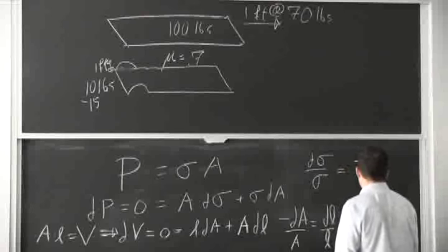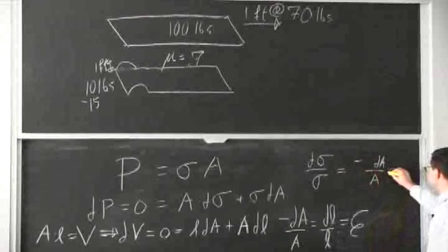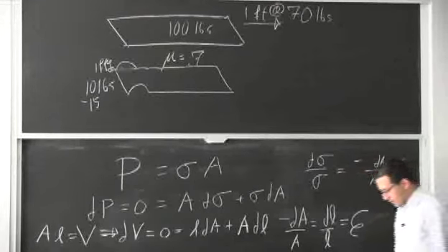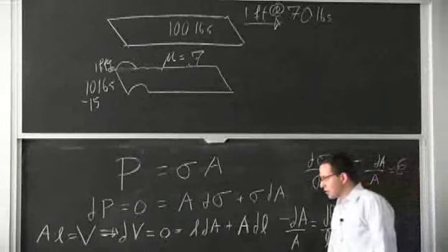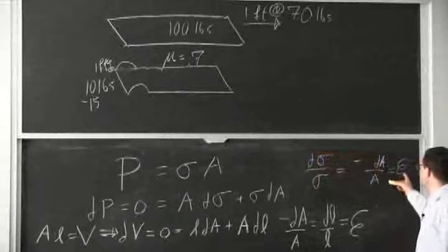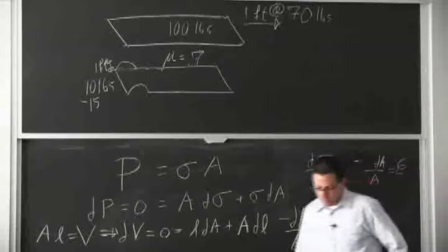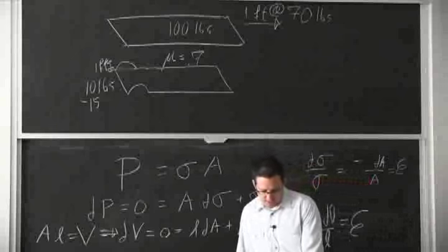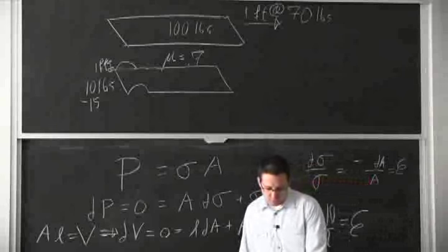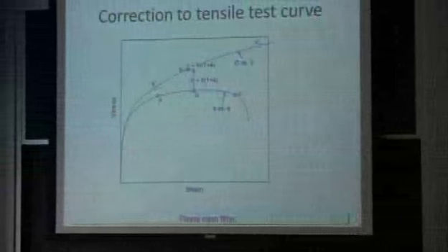It doesn't go to 0. That's the point, because you have sigma here, and you can actually reuse this equation with those variables to find that the value at B here of the true strain is your strain hardening exponent n.